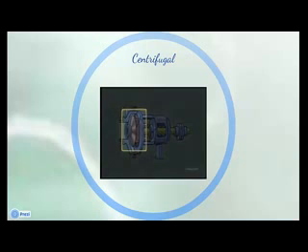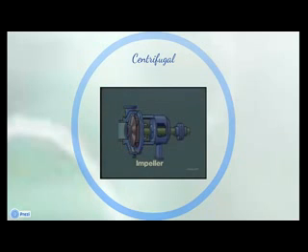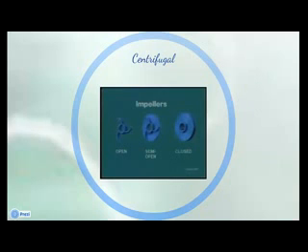This circular device is an impeller. The impeller fits snugly on the shaft and is usually pressed on. It can be held in place by several methods, but the most common is with a key and keyway. The impeller is the most critical part of a centrifugal pump. Why? Because its size and shape and the speed at which it turns determine pump capacity. There are 3 types of impellers: open, semi-open, and closed.